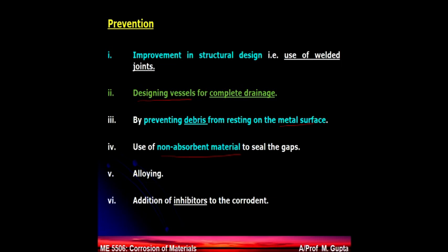Why do they use a white tape? It's just to seal the gap which will otherwise be formed because of the presence of thread. By that, it increases the life and minimizes crevice corrosion. So that Teflon tape is used to minimize crevice corrosion. Also, always go for better material.